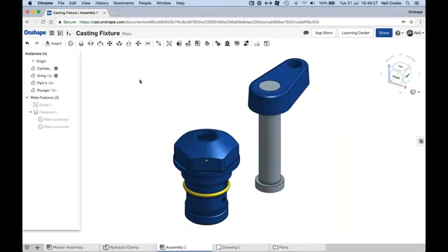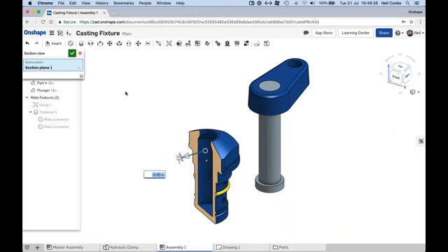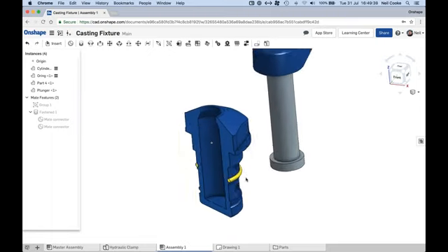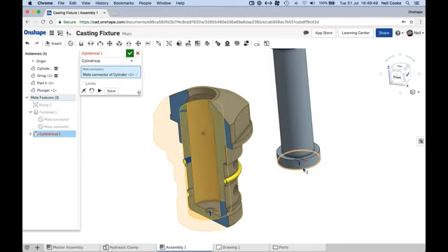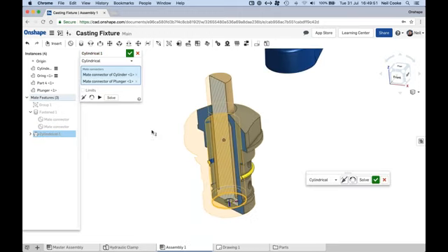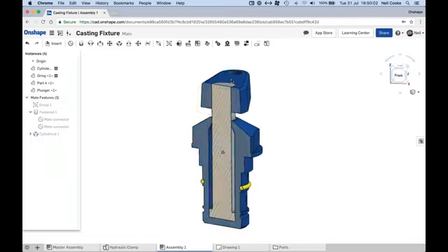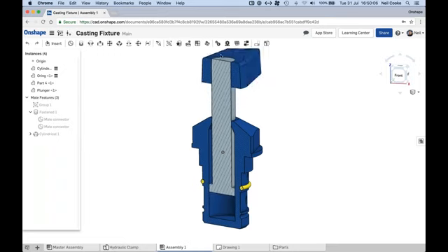Okay, and then finally, let me just do one more here, and I'll do a section view. So we saw section views before, just so it's easier to see what's going on. And I'm going to do a cylindrical mate. So this, again, we are adding degrees of freedom rather than removing them. So this is going to be perhaps the mate connector over the bottom of that face and the mate connector there. We'll position these two together. And if you press the play button, you can see this thing going up and down. You can also add limits in there to stop it going a certain height if you wish, but that's then going to give you both translation and rotation.